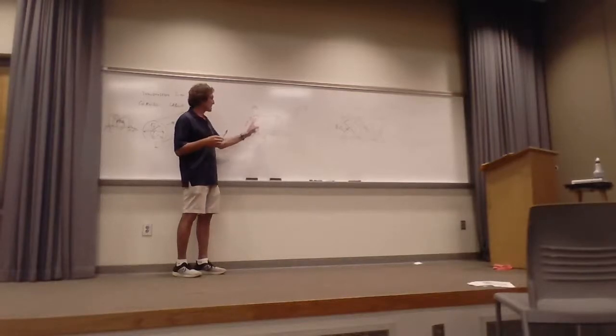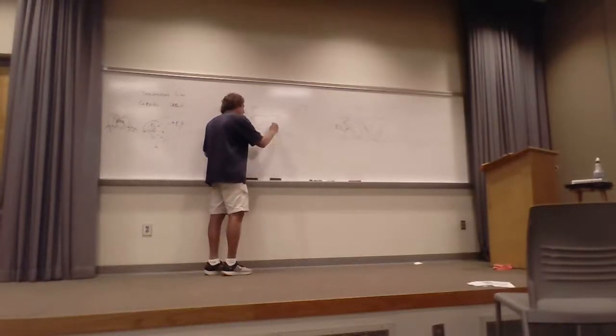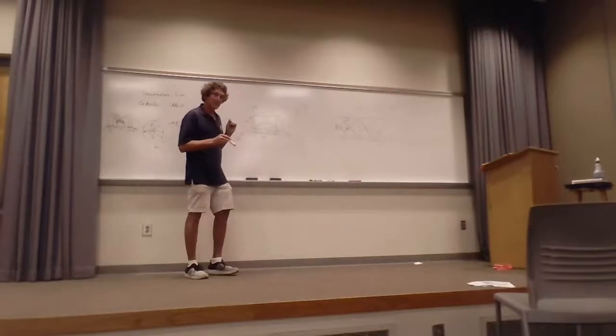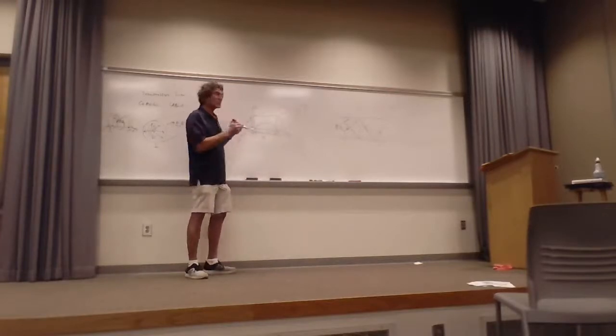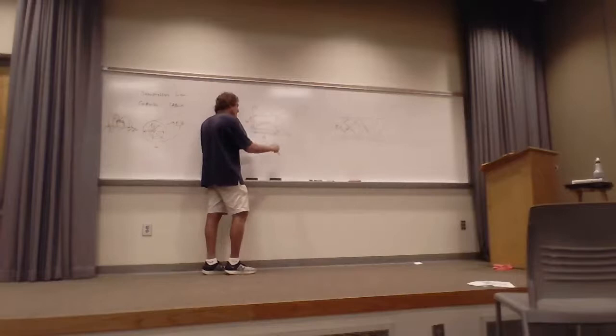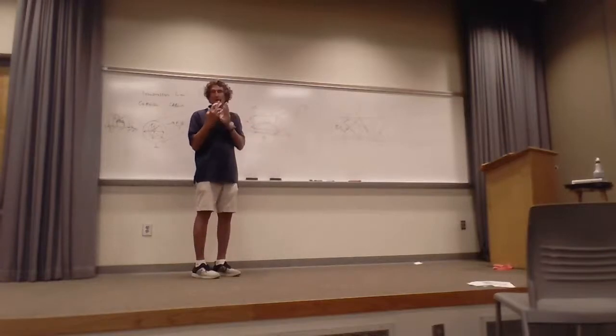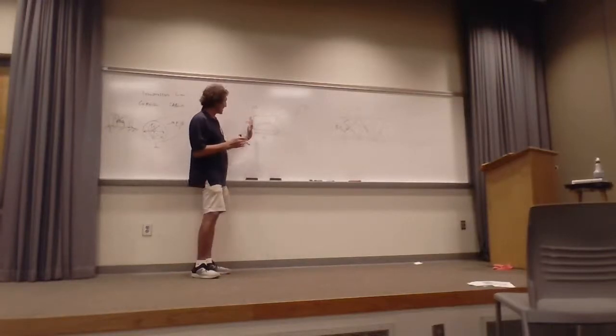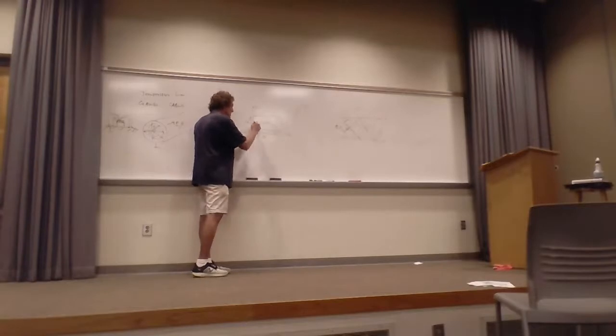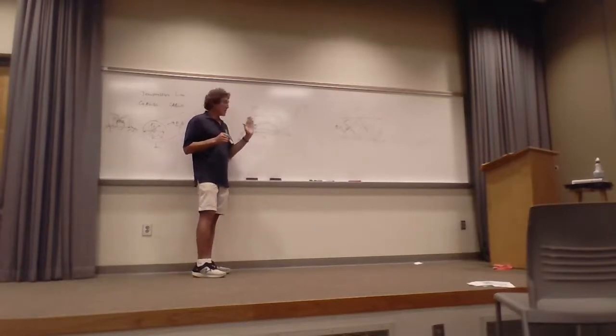What I mean is, there's a cutoff wavelength. If you take a look at A, if A is greater than B, when you get a half wavelength in this direction, anything that would try to be bigger won't work, because the envelope of the electric field in the vertical direction won't go to 0. Do you follow me on that?